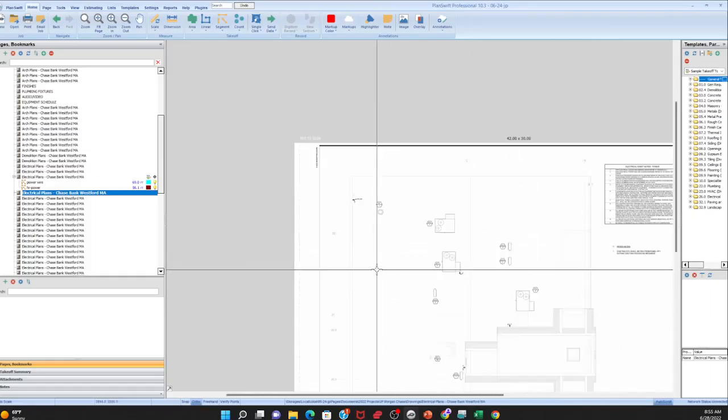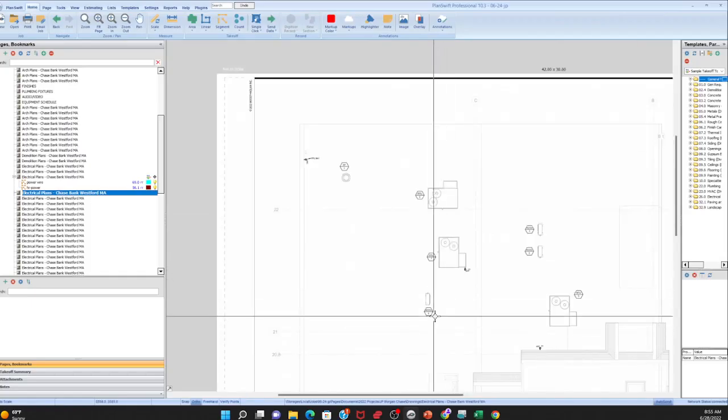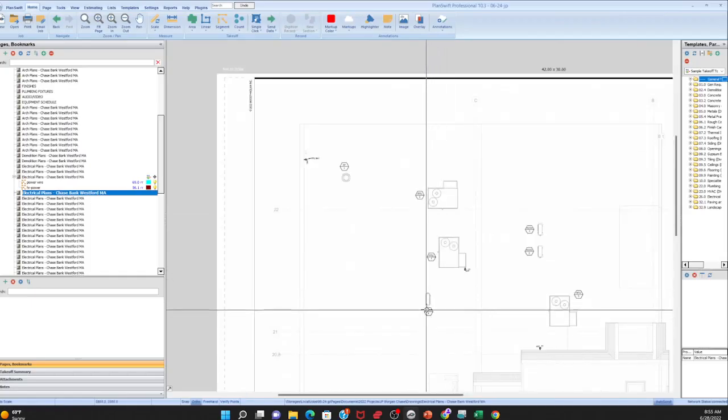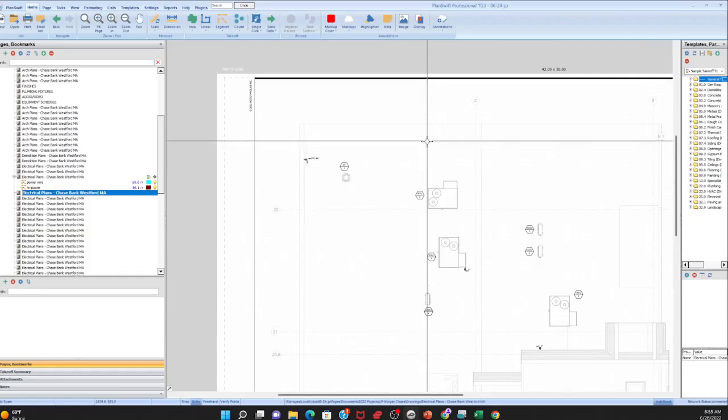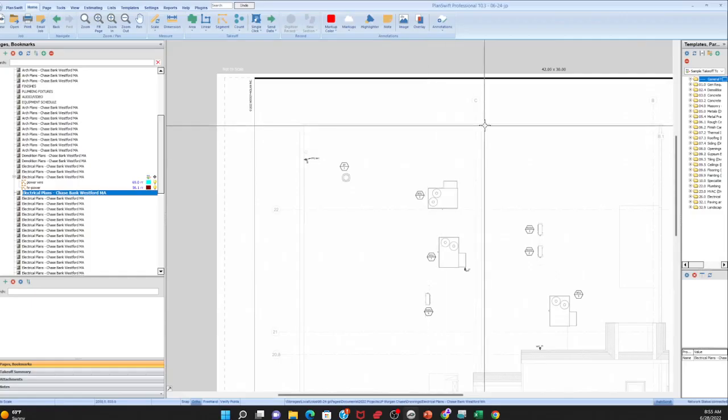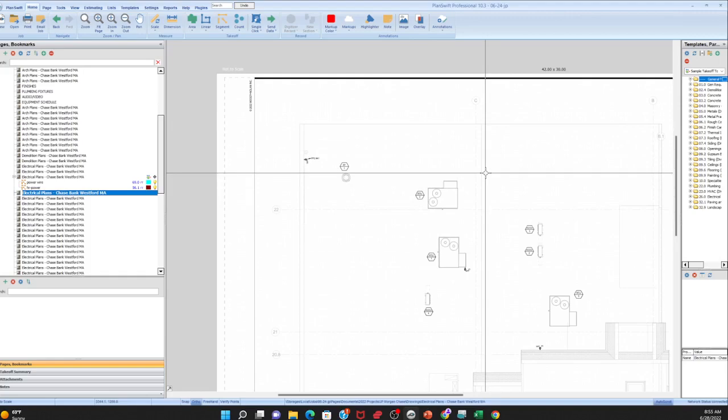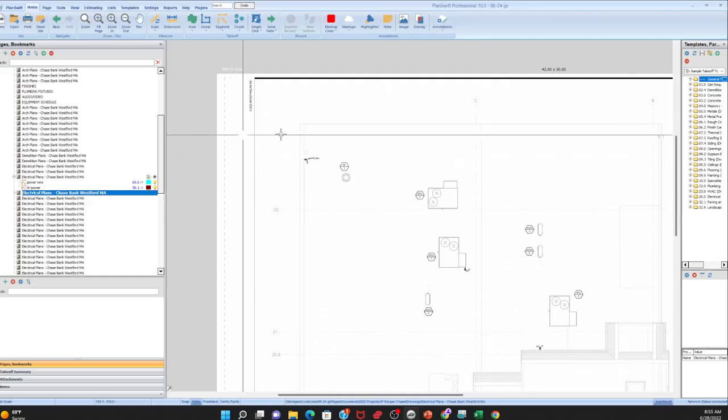Or we got to read the keynotes. It may tell us. But then the same thing here. If I have to run power, I'll just do it from right here to where I think the panel is and add 10 feet. Because, again, you're not trying to be exact, right? You're trying to get something that's an allowance, that's comparable to where you're not under. Okay? Okay, so that's the roof plan.